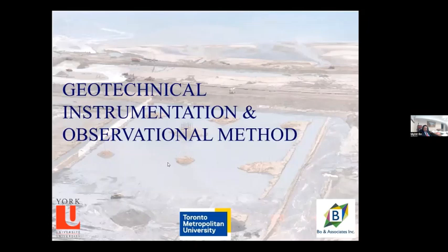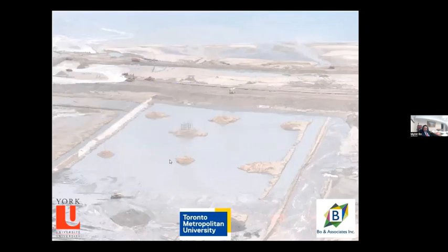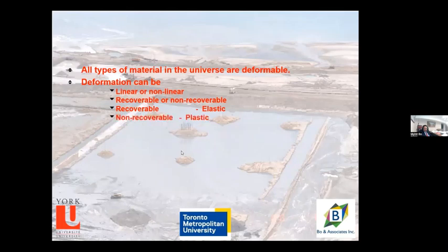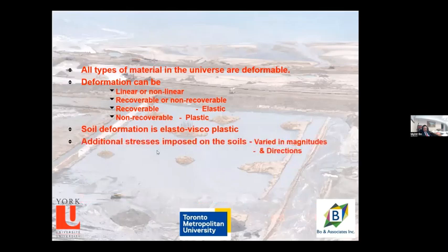Geotechnical instrumentations and observational methods. All types of material in the universe are deformable. Deformation can be either linear or non-linear. It is recoverable or non-recoverable. Soil deformation is a complex elasto-viscoplastic behavior. So in addition, the additional stress imposed on the soils varies in magnitude and directions, and also varies in rate of loading. Therefore, predictions are rarely the same as the performance.